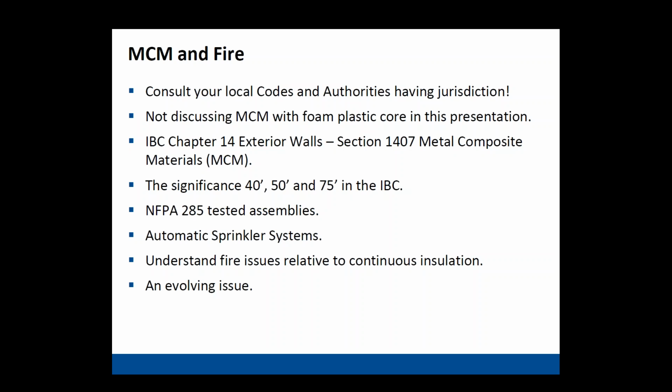No, I don't. We work hand in hand with the material manufacturers, and the way we view it is we want them to create the demand and drive the usage of the product. Once a designer decides that he wants to use MCM on a project, that's where we can come in and sometimes help save a budget or keep an EIFS off a project versus using MCM, because oftentimes just moving a panel joint could make a $5 a square foot difference in installed cost, or combining two panels, or asking, is this panel joint important to your design, or did you just put it there because you thought you were supposed to?